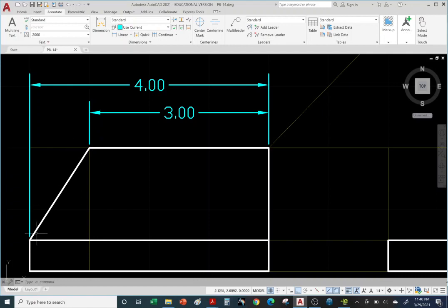And once again, look at the gaps. Okay, let me show you something that is incorrect. You do not want an extension line. So right now we do have the gap at the bottom. You don't want an extension line overlapping an object line. This is incorrect, and I will take points off.